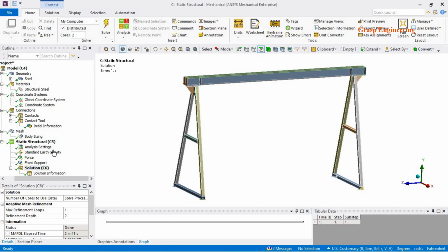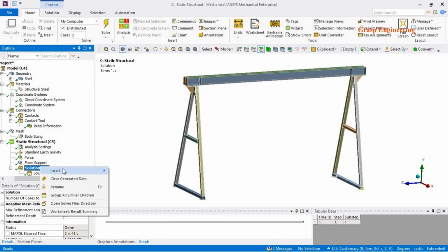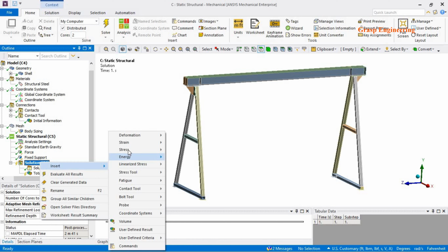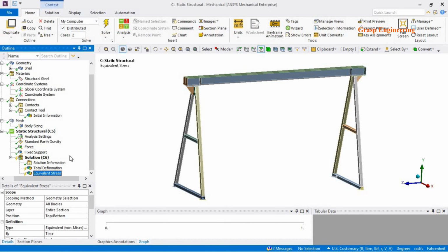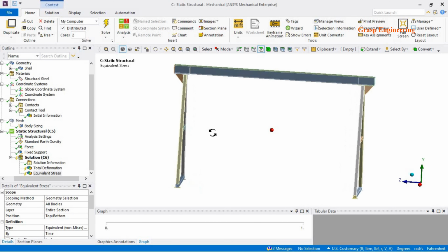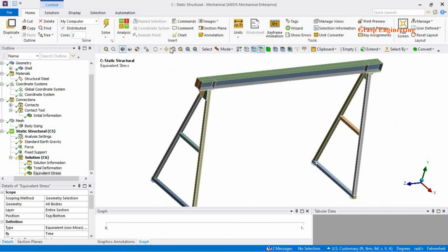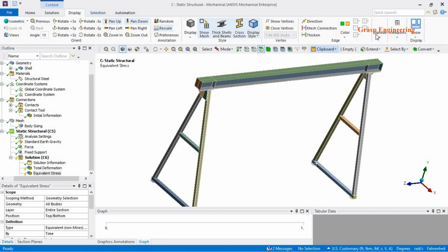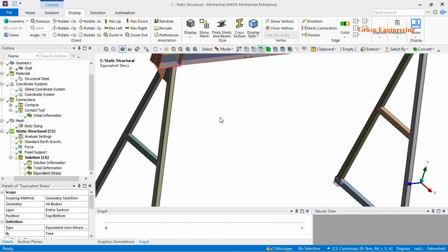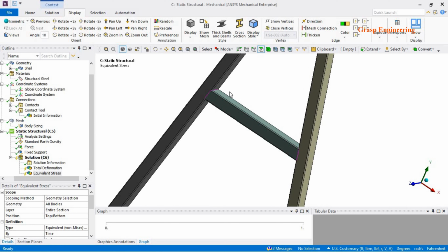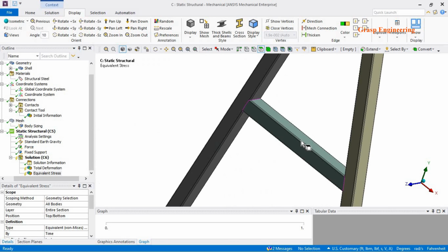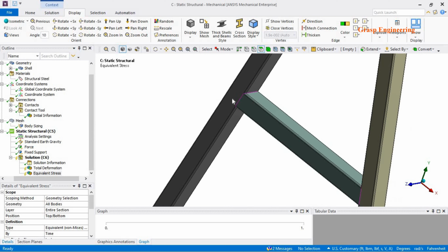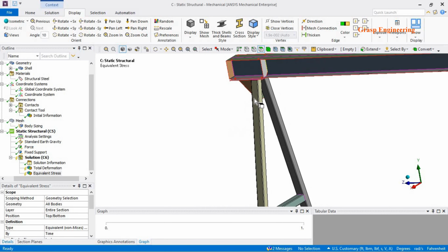So now if you see, our simulation is performed. While doing these simulations, once you have given run, if you come across some error or rigid body motion, it means that your structure is not completely connected. So in that case, you need to check each and every connection, right. So here you can go to the display tab, here connections, and here you just check. Right now you can see that if the respective edges are red, it means that you need to define the connections.